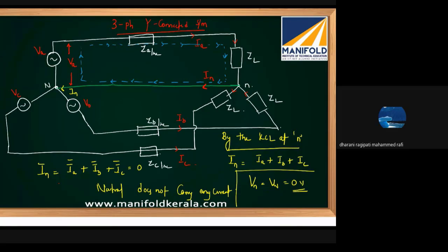So when the currents are balanced, automatically it ensures that all the voltages are in balanced condition, induced voltages are balanced, terminal voltages are balanced, voltage drops in the lines are balanced, and the three phase impedances, whether it may be source impedance, load impedance, or the line impedance, all of them are identical, all of them are the same in all three phases. So current balance will ensure everything. Okay, this is about the three phase balanced power system.